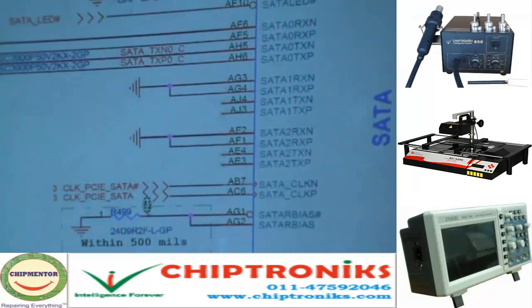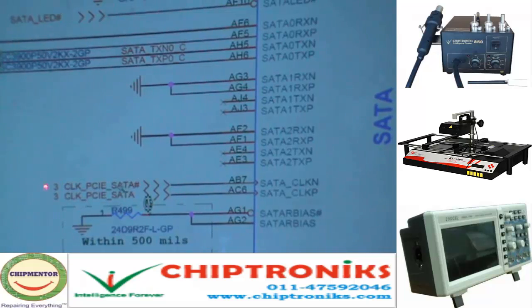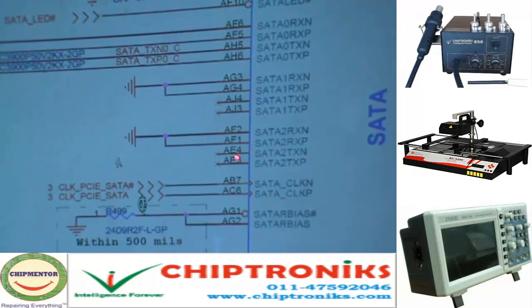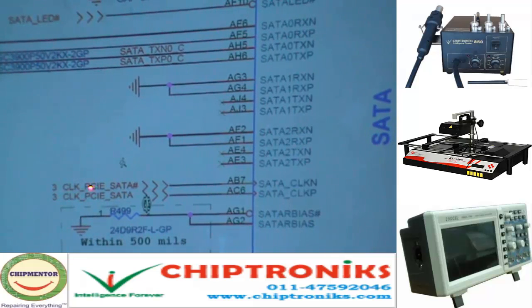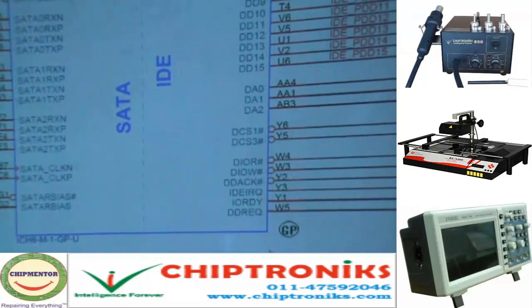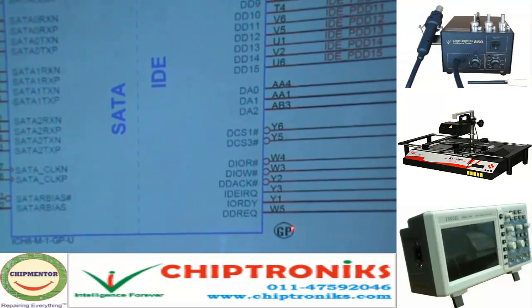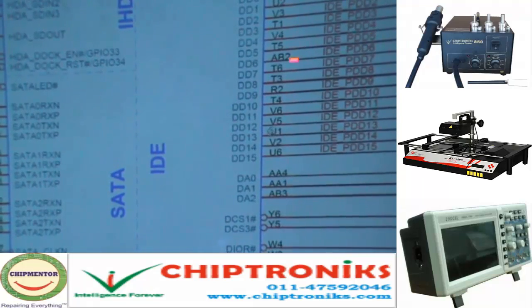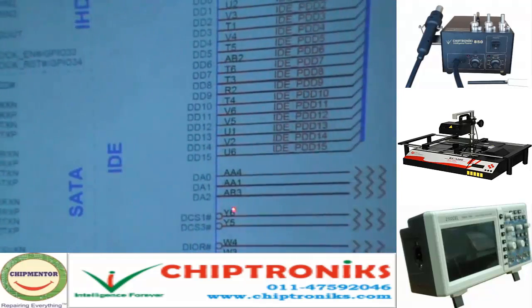The important signals for SATA working include the clock signal also, which is coming from your clock generator IC. If a problem occurs like SATA not working, then we have to check this signal, whether the SATA signal is coming or not, and whether voltages are coming to the SATA controller of the ICH. We'll refer back to this. As I told, this DV231 board has an IDE DVD ROM, so this is going to the DVD ROM connections. IDE.